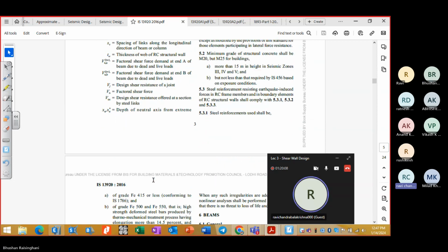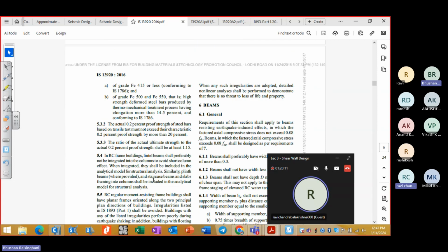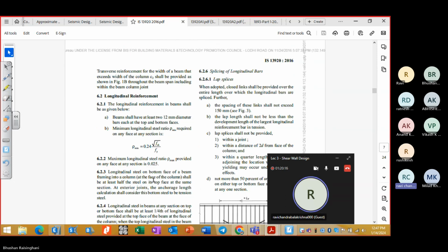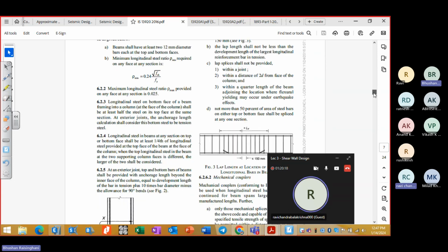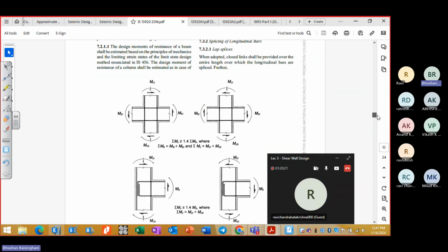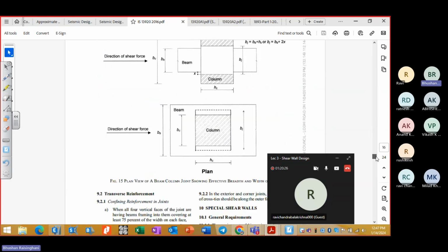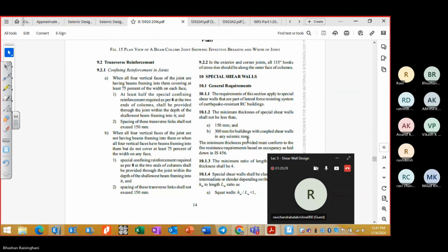Yes, sir. There is nothing. But I'm seeing that many people are connecting the beam with 300 depth also. They are saying that it's a coupling behavior. I don't think so. It has to be dominated by shear, not by bending. So a simple arrangement is: if your beam is dominated by bending, then it is not a coupling beam. Design has to be shear dominated. Your size has to be such that bending will not cause failure. It is mostly shear governed action.